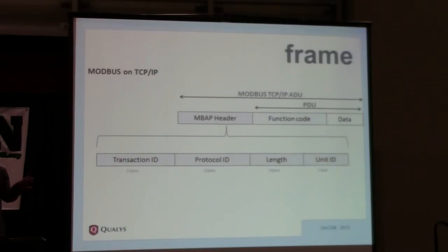The header has basically a transaction ID. As I mentioned, there is field equipment here. Let's consider another example where the HMI wants to know what the pressure is. The HMI would say, hey, this is transaction number 1, tell me what the pressure is. And the response comes back saying, hey, the question that you asked, which was in transaction number 1, this is the answer for it, and this is the pressure. So transaction ID is nothing but a unique question number and a unique answer number.